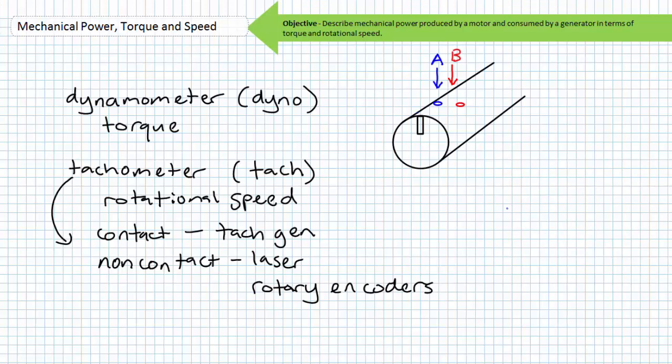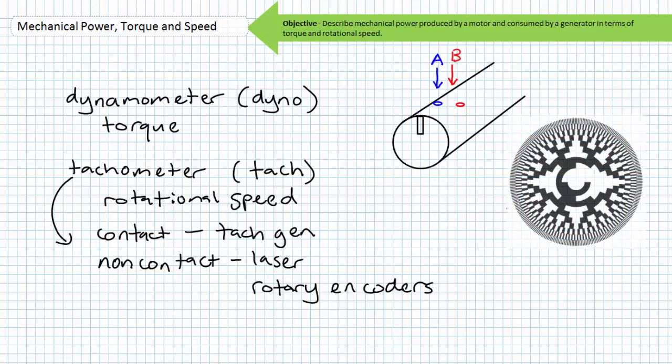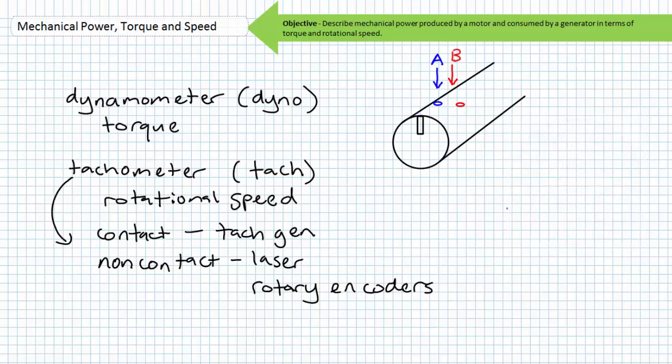There are varying levels of complexity of this type of rotational speed measurement, and it is sometimes referred to, quite surprisingly, as A-B encoding, incremental encoding, and/or quadrature encoding. We'll get to these methods in much later lectures. Much later, we might visit absolute encoding, in which each angular position on the shaft is assigned a specific binary combination, utilizing something called gray code, where only one bit position changes for each transition to the next position. For now, just think of these advanced methods as super fancy means of determining not only rotational speed and direction, but also relative or exact position of a shaft.